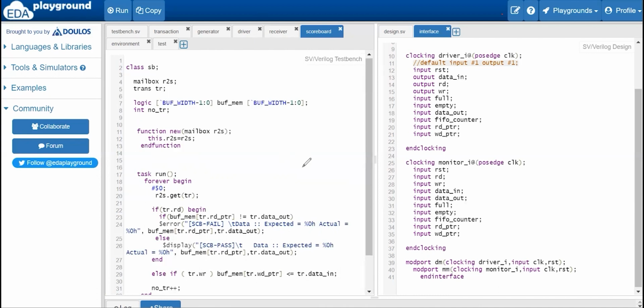So how can we generate the golden reference value here? Nothing but by writing the expression. Suppose our FIFO is doing some functionality. According to that functionality, we will write some program in our scoreboard to satisfy some conditions. If the condition is satisfied, automatically the output will be obtained. Once the reference value is generated, we check that with the main output. So that is the scoreboard logic.